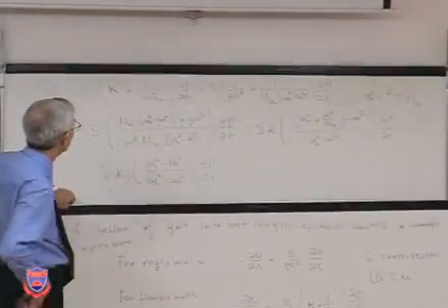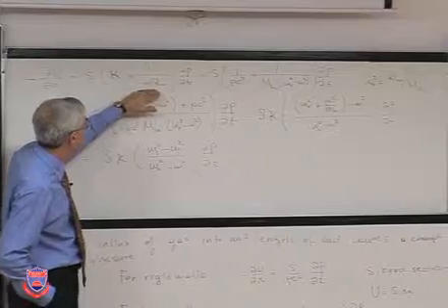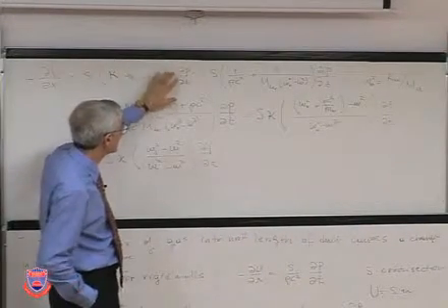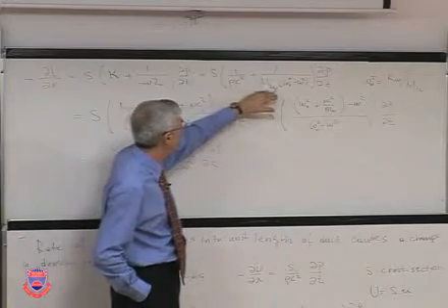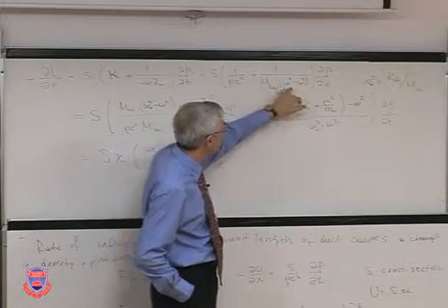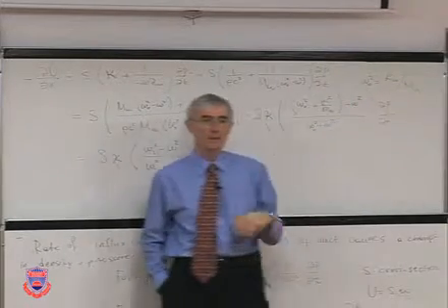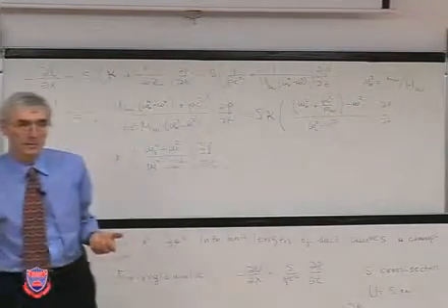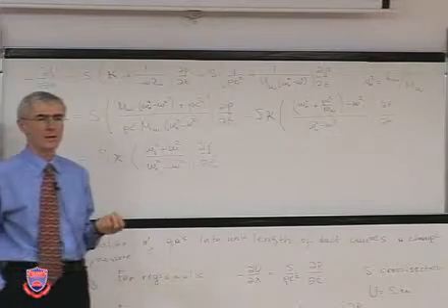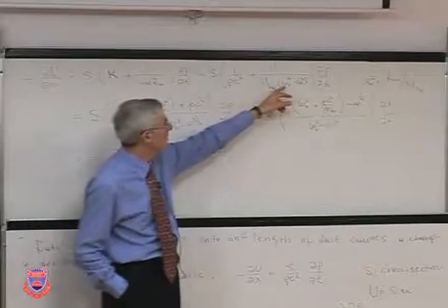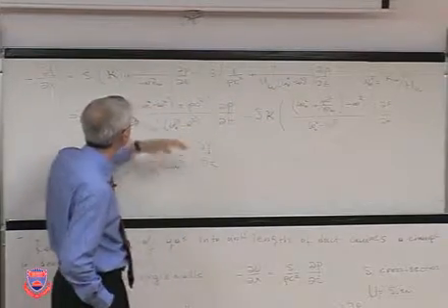If you substitute the full impedance instead of just the stiffness and make appropriate substitutions, omega 0 here is stiffness of the wall divided by its mass per unit length. So it gives a resonance value, okay? At a certain frequency it resonates. And so this is the wall resonance.